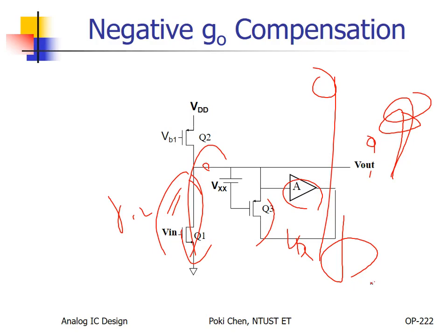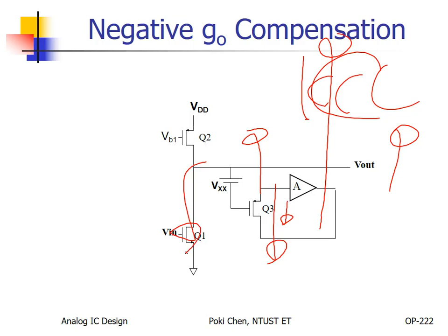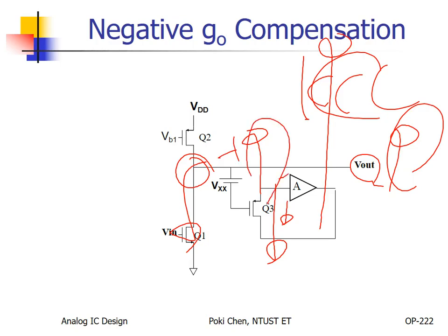So it means what? Because from the beginning, you can see it conducts some current, right? And then if you increase it, as I mentioned, this will increase substantially. So the current here will be decreased substantially. So what does it mean? Some kind of AC current flows out instead of flows in. According to KCL, that is, I mentioned already. If you increase the V out, then the AC current here will increase, and according to KCL, this AC current will flow in that way. Oh, congratulations. What does it mean? This is the so-called positive feedback.